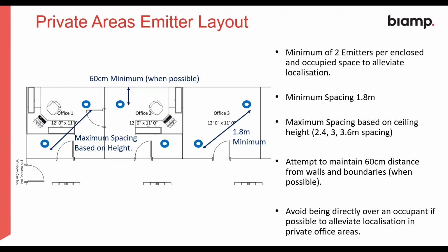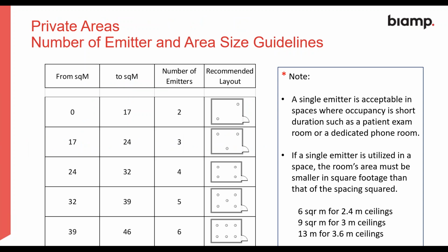And when we come to commissioning, then we might need to adjust the tappings on the emitters. If we have a room that's only used for a short period of time, we can go down to 1 emitter. And this is shown on this table here.